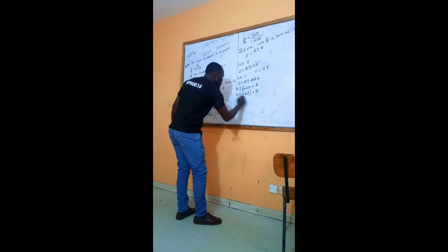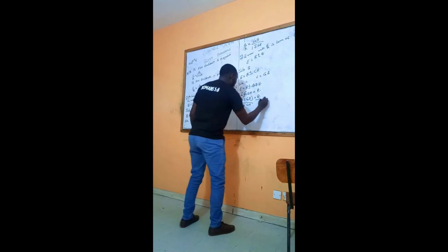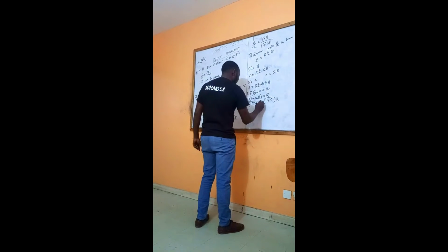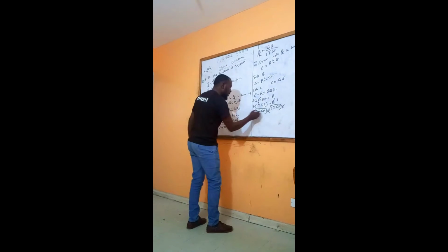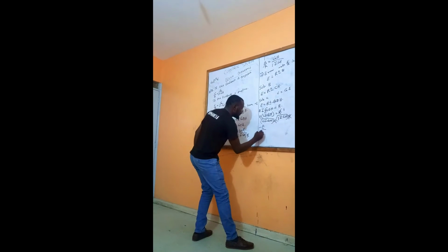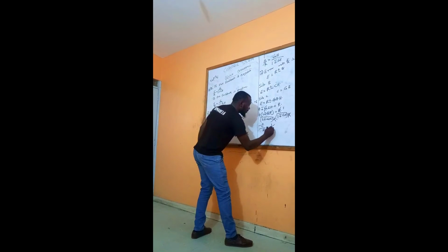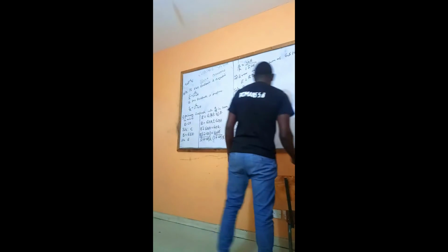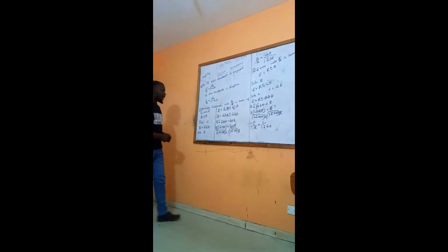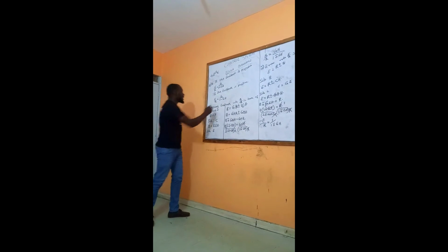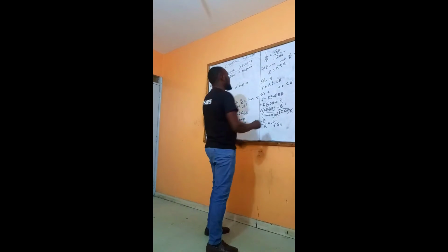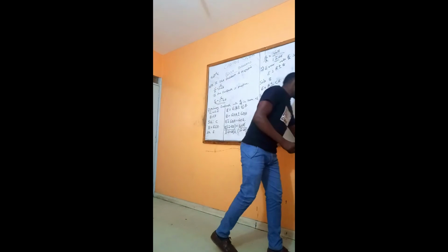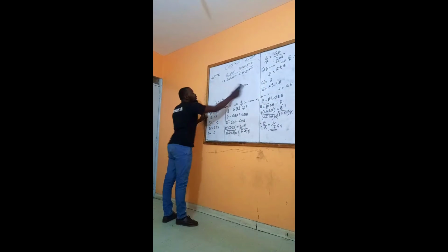Now, divide both sides by 1 minus or plus GH. Don't forget about this R and the R. Now this one and this one will go. Now we have E divided by R is equal to 1 over 1 minus or plus GH. Don't forget about the formulas while we are solving this sum. The first formula was here, the second formula was right here, and the last formula is here. So, when you are dealing with the block diagram, there are some rules that you need to follow.